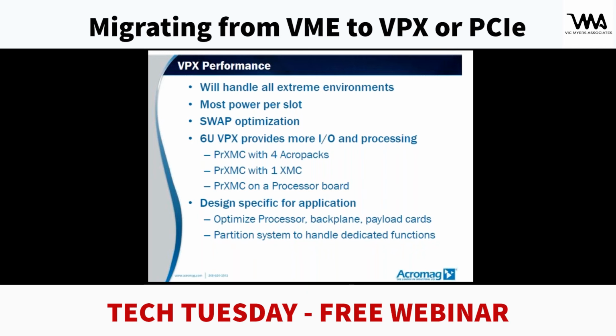For example, a graphics processing unit or a field programmable gate array, and get an extreme amount of processing in one slot. Another example would be taking a 6U processor board and adding a processor XMC. In this case, in theory, you could be running 2 different types of processors, and you could be running 2 different types of operating systems all in one slot.